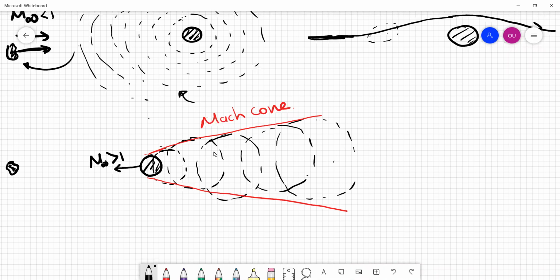As the object moves towards this fluid particle, almost instantaneously, at that very instant, it realizes that there is a solid object, so it has to adjust its position almost instantaneously. Generally, that's what happens when we have a shock wave, an oblique shock wave, for example. The streamline is coming like that, and it has no idea that this object is here, and suddenly, almost at this instant, through this oblique shock wave, it has to adjust its direction.